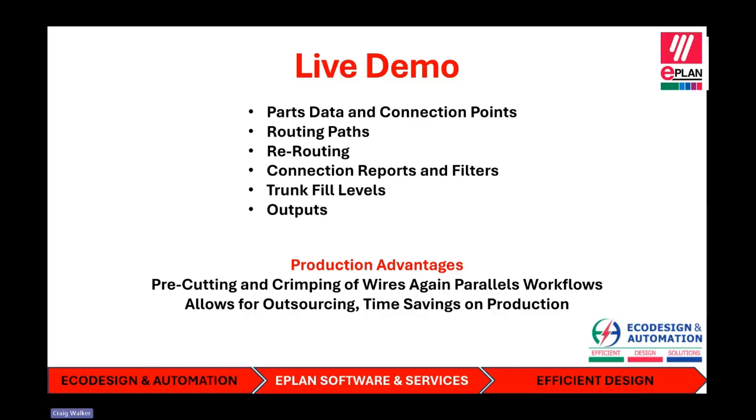So obviously the advantages of this is pretty much the same as the DIN rail and the DIN and ducting, in that you can remove it from having to wait till you've got the last stage of production done. You can pre-cut, crimp, and label all your wires. You can have them ready in groups of color or whatever you need, so that once everything's mounted on the panel, you can put it straight onto that panel, and you're not waiting around. And it also saves time, because manually pulling off a roll of wire and then terminating individually one by one can be a very slow process.